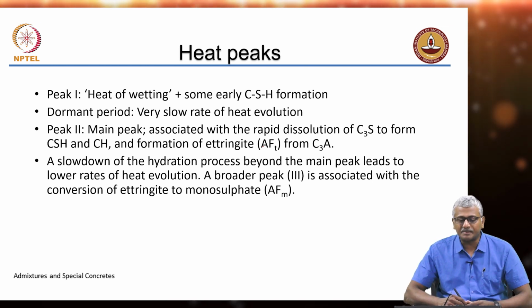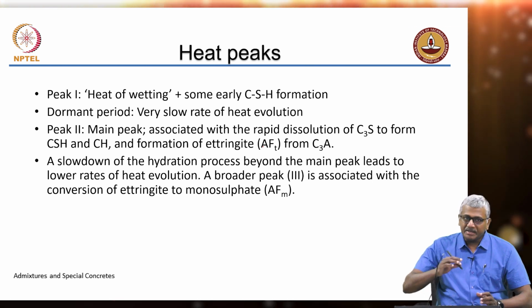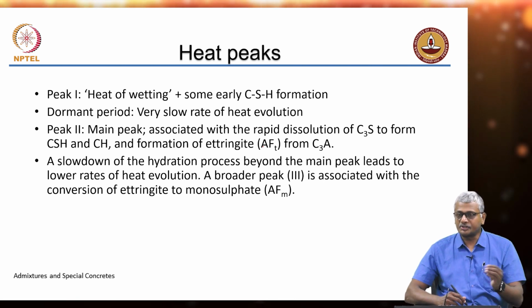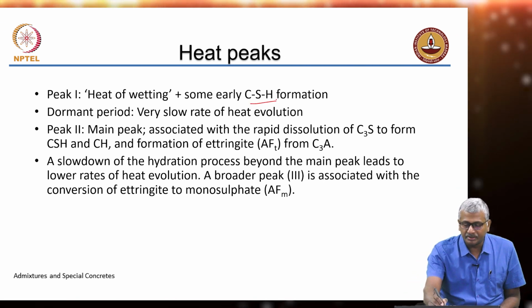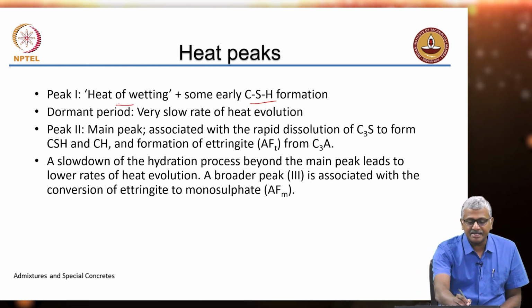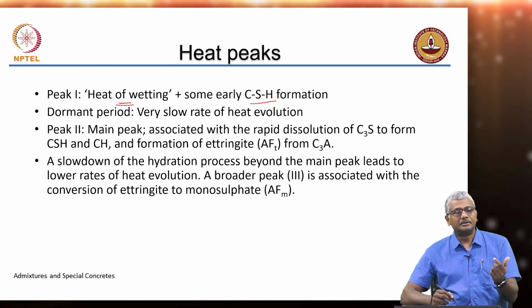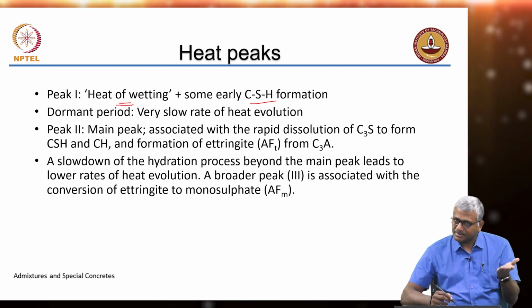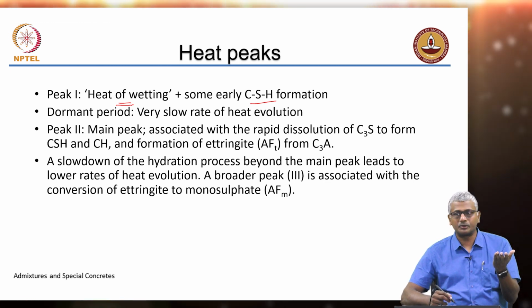So, just some descriptions about what these peaks in the rate of heat evolution curve are, okay. As soon as you mix cement and water, there is some initial CSH formation and this heat of wetting. Any powder, right, any powder, if you wet any powder, there is an initial heat evolution.